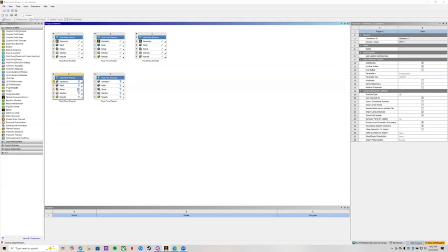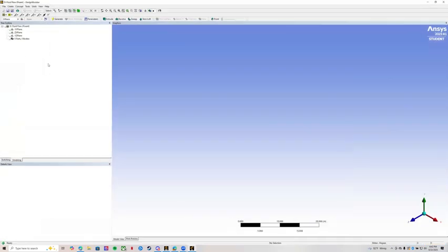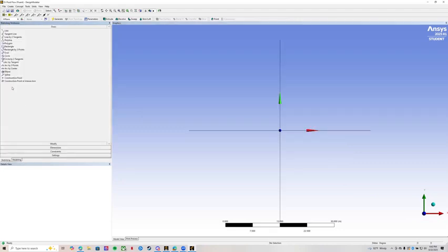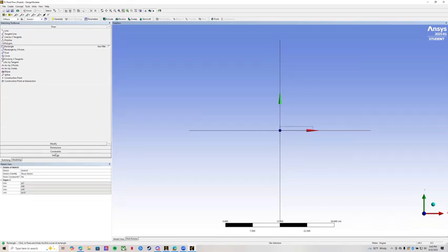And so we were given the specific instructions for this assignment to follow the simple formula of height times 150 is what equals our length. So first things first, we're going to draw our geometry out with a sketch here. Go down to sketching. We're going to pick a rectangle. We're going to draw our point from the origin. We're going to select the z-axis. That way we can look at everything from this xy plane. Create our first bit here, which is our rectangle.